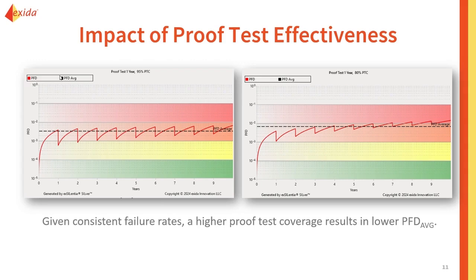So you see how important these parameters are to your SIF design and ultimately to your achieved SIL and your achieved risk reduction factor. And so we want to make sure that going into the O&M phase, we're carrying out these maintenance tasks just as we specified in our calculation to the best of our ability.